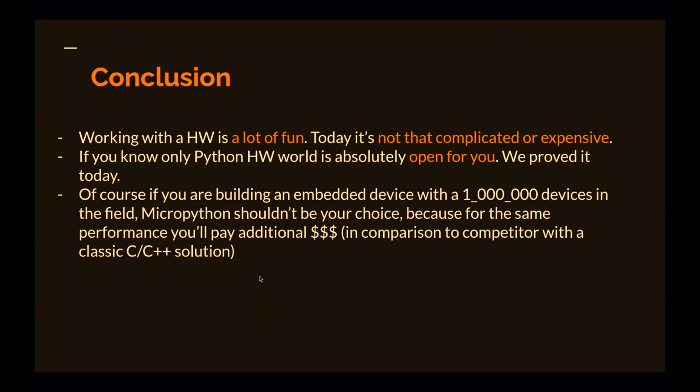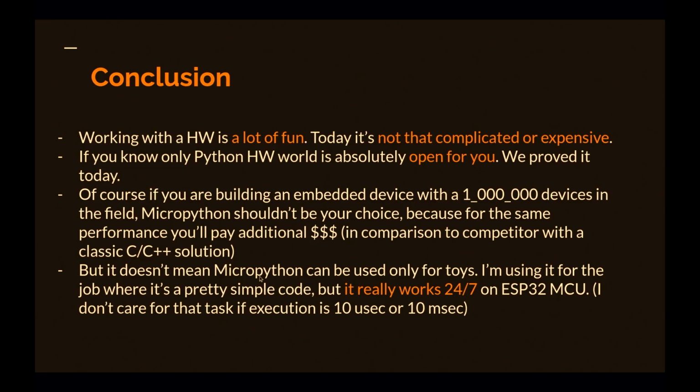If you are an investor and you decided to use your Python developers to deploy 1 million devices with MicroPython, I don't recommend doing this, because your competitors will save on BOM, purchasing cheaper hardware, while delivering the same level of performance. But at the same time, MicroPython is not only for toys. During my job, I did a project that works 24/7 on an ESP32 microcontroller, and it solved our problem. We have maybe 30 or 40 setups running on a daily basis. I don't see any problems, but I did not care if the execution took microseconds or milliseconds or even seconds. It did not matter for me.